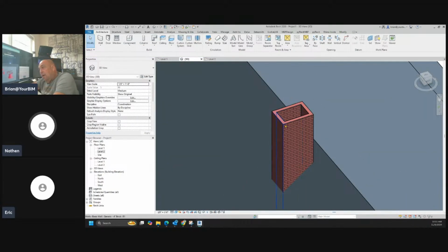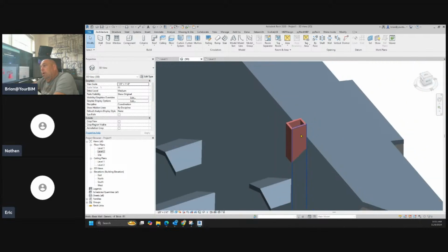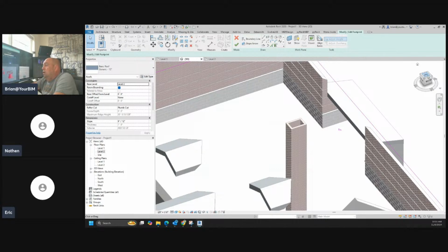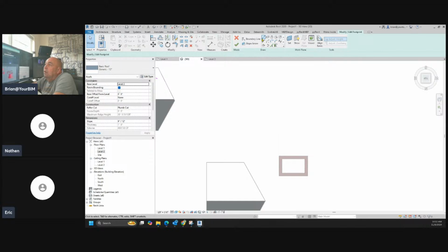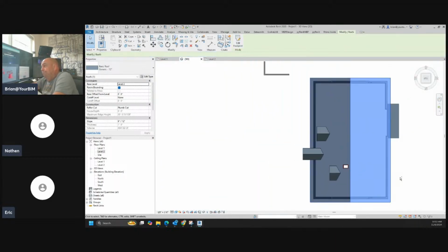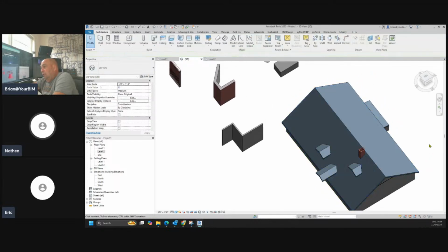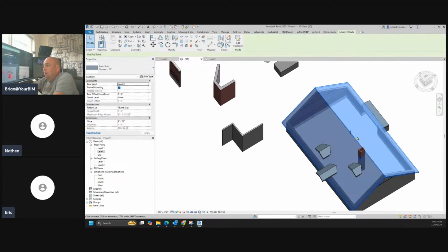Is that hollow in the side? Does that cut a hole through it? If you wanted to cut a hole through that roof, you would probably be using one of these guys here, would be one way to do it. Or remember what Eric told you, right? Island detection methodology. If I come in here and I draw without a defined slope right on there, what's our rule? Remember how we did that with the floor slab, right? Yeah. Oh, I got you. Okay, yeah. It just slices right through because you slap the roof on top of a roof. Technology, right? And here I'm going to draw another one.